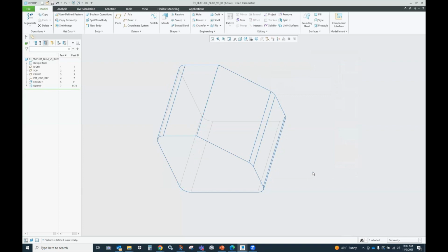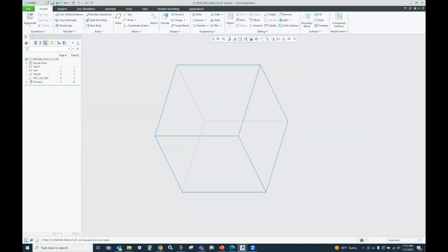So I'm not sure who asked that question, but does that answer your question? Yes, it gives me a solution. Okay, right. So again, you can select one or more edges to be excluded. You can even create that datum reference feature to have multiple chains in it, right? I can create this datum reference feature.